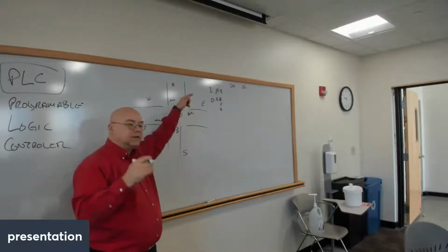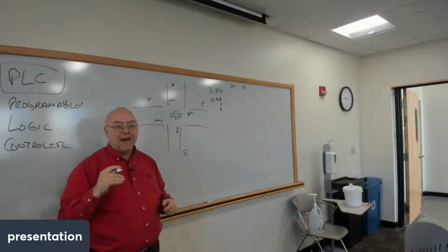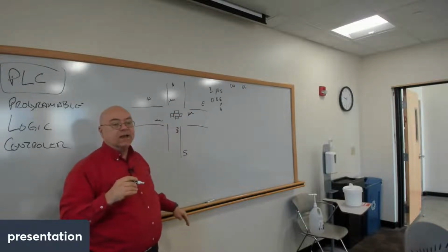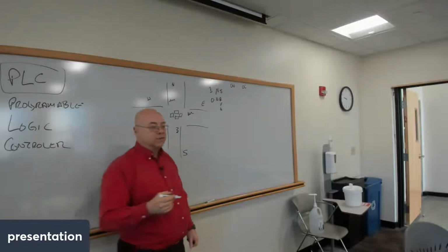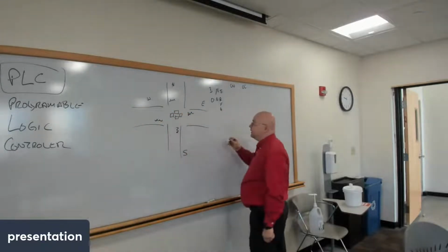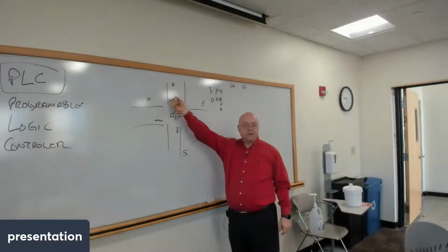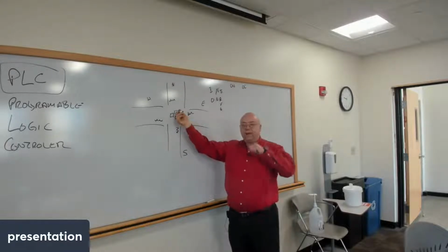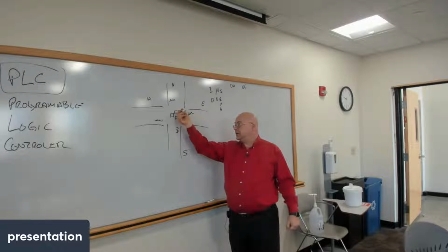The order that you put things in your ladder diagram matters, but it's also important to know that it reads all the statuses and then it decides what to do. So we said if the sensor's active and the light's green, do nothing. But if the sensor's active and the light's red, then you check the other sensors, maybe you see what's going on, you decide whether or not to do the time thing, and you set.